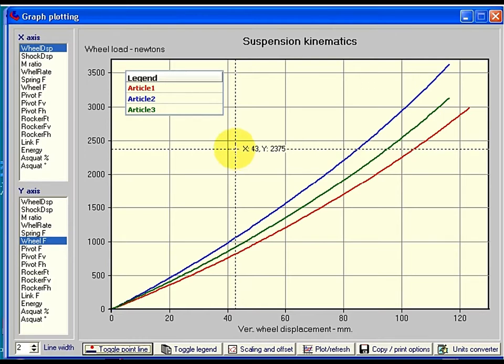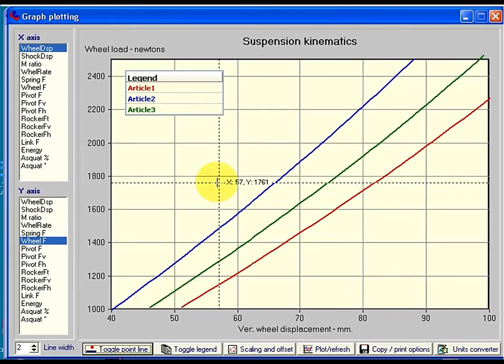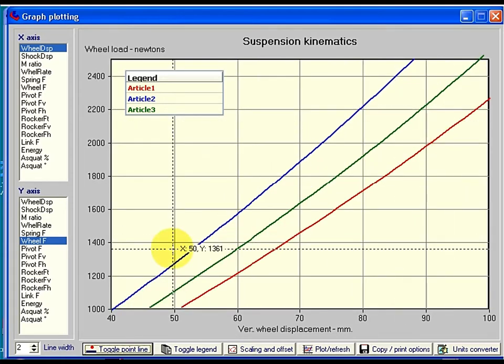We can drag the rectangle for the zoom parameters by holding down the control button and the left mouse button and then forming a rectangle. So in this case we'll zoom in on an area which is the same as the grid lines which are bordering the dotted area which I've just dragged out. So I'll let go of the control and the mouse button, and now we've zoomed in on that particular area.